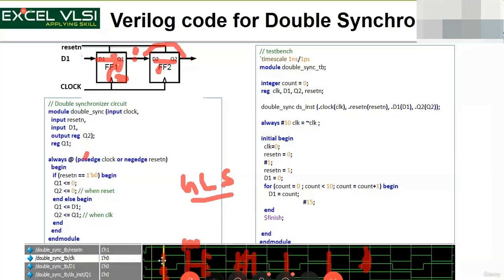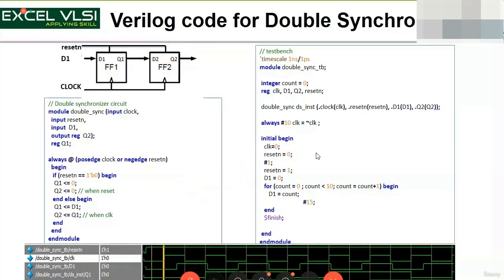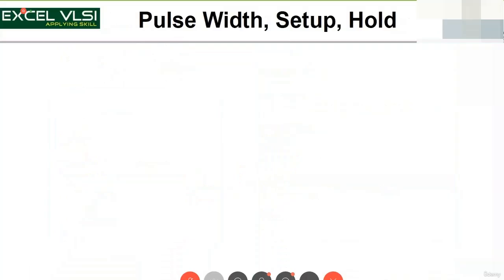Okay, and this functional simulation only with the gates, it is one level, that is the zero delay simulation. Second is with delays, that is gate level simulation with delay plus timing, that is SDF. So now both of these, right, so this is called dynamic simulation. Okay, so in dynamic simulation, we run the simulation and then check whether my circuit is meeting the timing. Okay, so that is one thing.